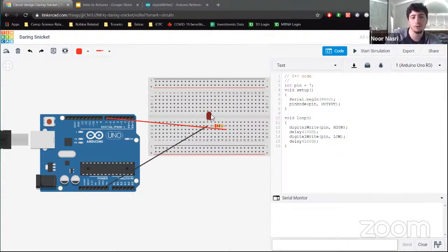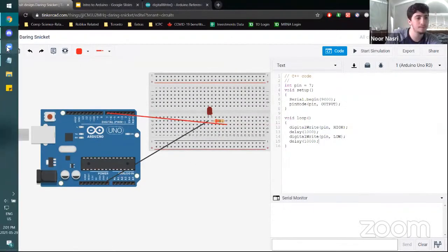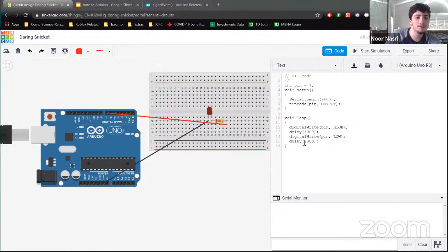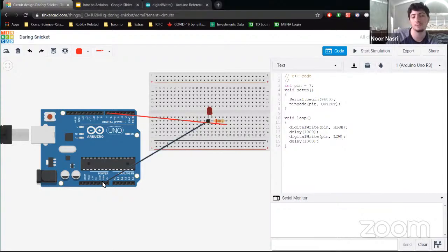What do you mean flash? Like it's the one LED or both of them? Yeah. So the trick with two LEDs is you don't want to use the same pin for both, because you want to control them differently. So you want to just repeat this exact same thing. And then the only other really important thing is recognizing that the ground, they can both go to the same one. So if you rearrange this a little, you'll be able to make it more generalized, where they're both looking nice together. You could also just connect a completely different one to repeat the experiment. And the only difference really becomes what you're doing here, which line goes where.